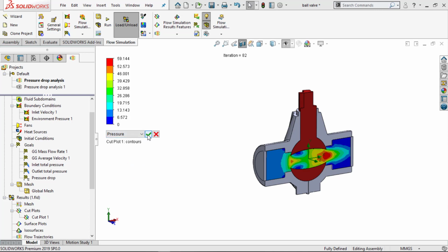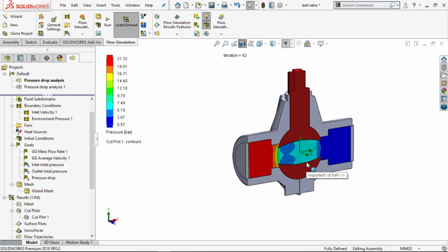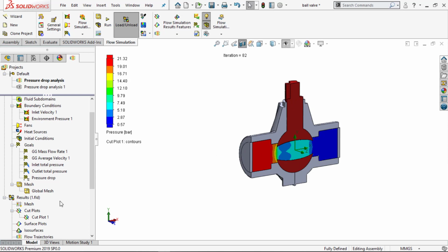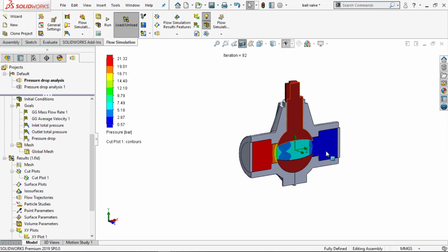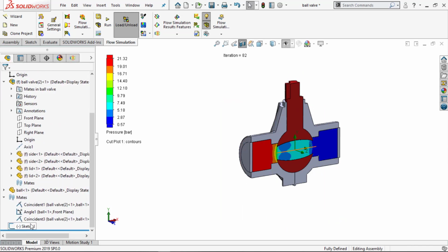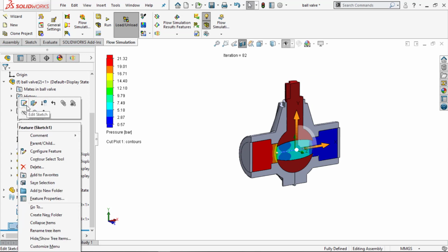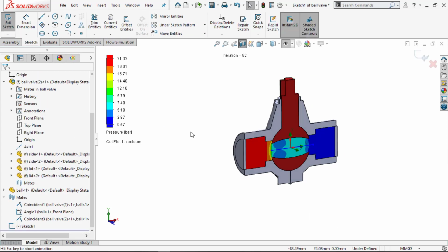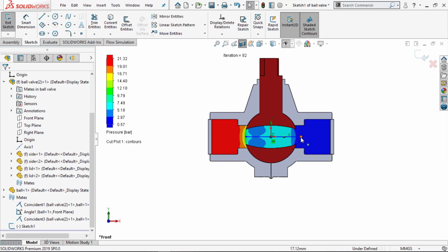to the pressure drop down. You could see how exactly it is changing. So at the initial position the velocity is very less, the pressure is very more. Pressure and velocity are inversely proportional. Okay, so let me just see the sketch here, which I have simply drawn at the ball wall location so that I can show you the xy plot from here to here, how the pressure and velocity are changing.